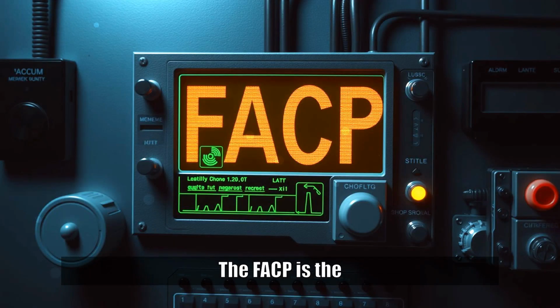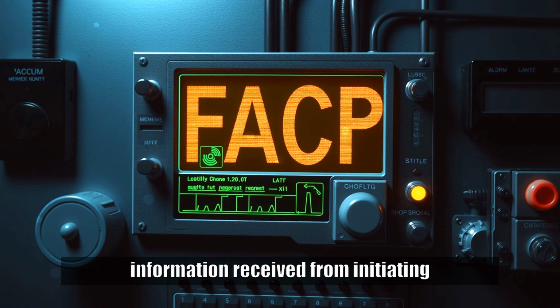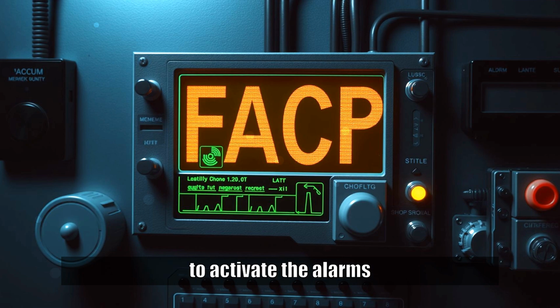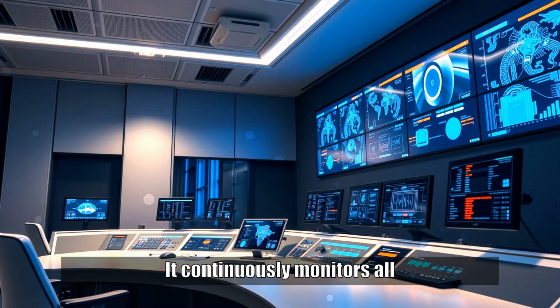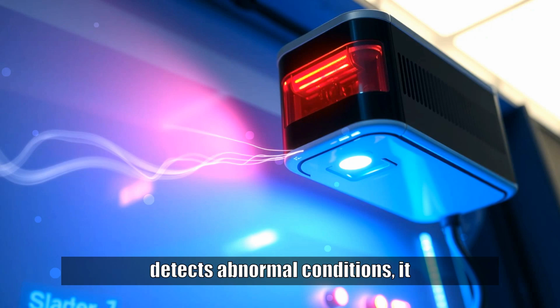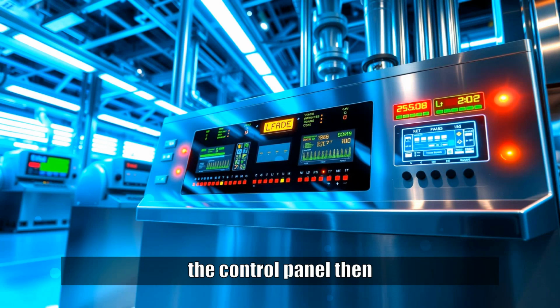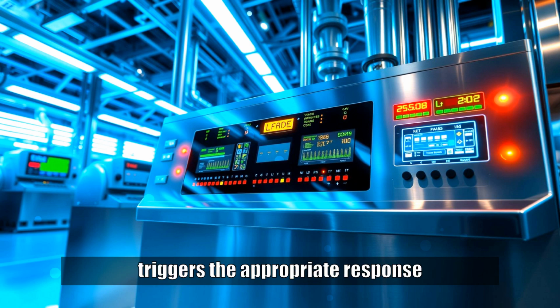The FACP is the centralized unit that processes information received from initiating devices and determines whether to activate the alarms. It continuously monitors all connected devices for fire conditions, system faults, or tampering. When an initiating device detects abnormal conditions, it sends an electrical signal to the panel. Based on pre-programmed logic, the control panel then triggers the appropriate response.